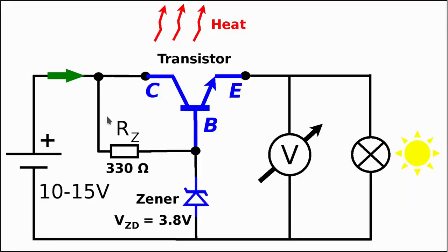Let's go! In the 9th episode of the switch mode power supply repair series, we introduced this circuit where there is a series resistor put in series with a Zener diode. The Zener diode is then producing a reference voltage, and this reference voltage is put on the base of a power transistor, where the power transistor is operating in the emitter follower configuration.